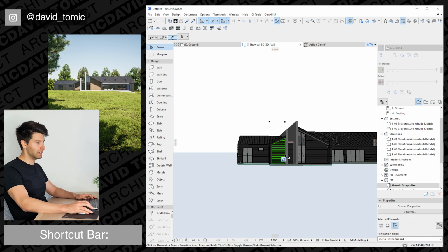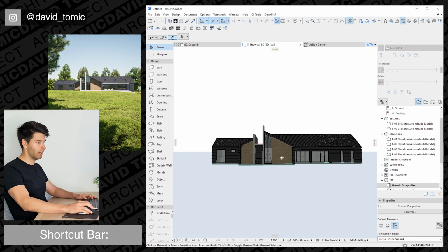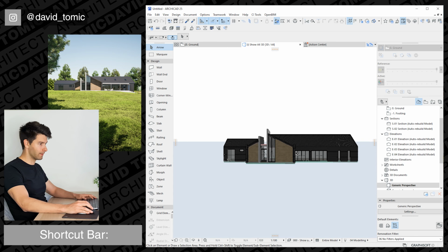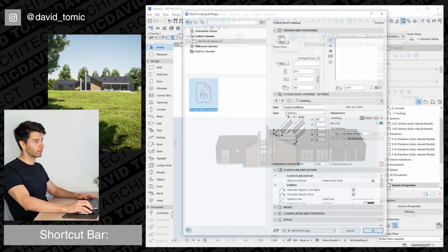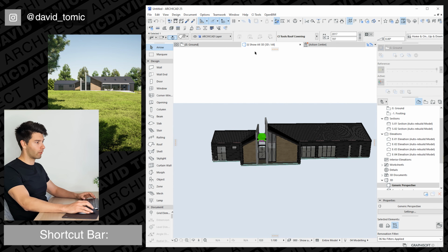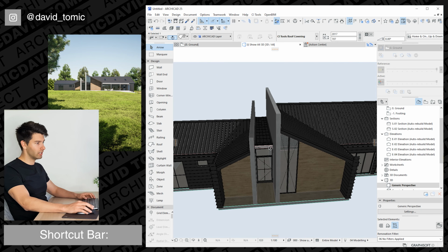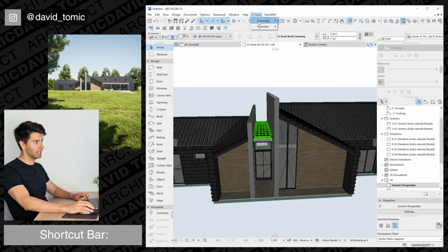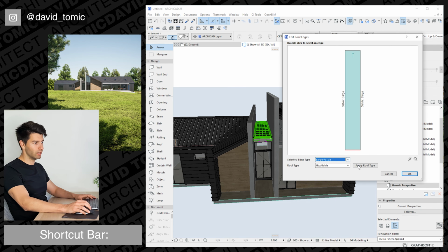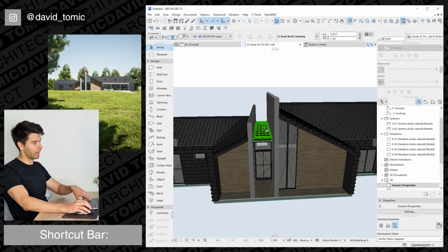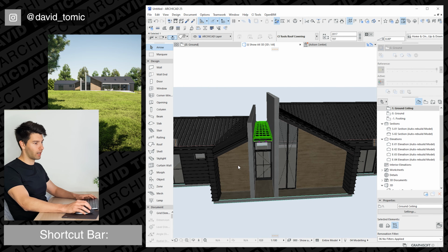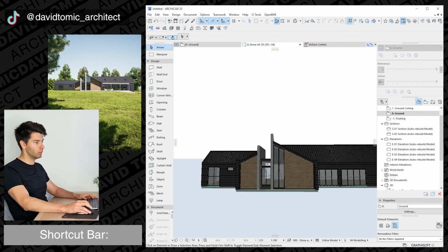Coming back into 3D, we can delete those two there, we don't need them, and we can delete that front door there as well, we do not need that. Finally, all I'm missing here, CI tools covering, roof covering, just clicking OK, creates that same wraparound roof. And to change the actual spacing here of what we see at the edge, CI tools covering, edit roof edges. This side here needs to be a barge, not a junction. Okay, and I can see my framing coming through, so Command T, coming to framing, let's just include framing, tick that off for the time being, and we lose our framing.